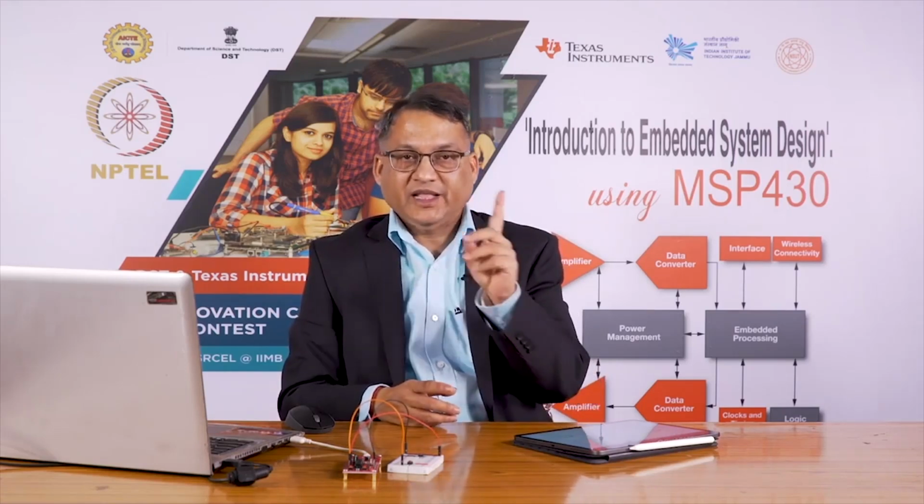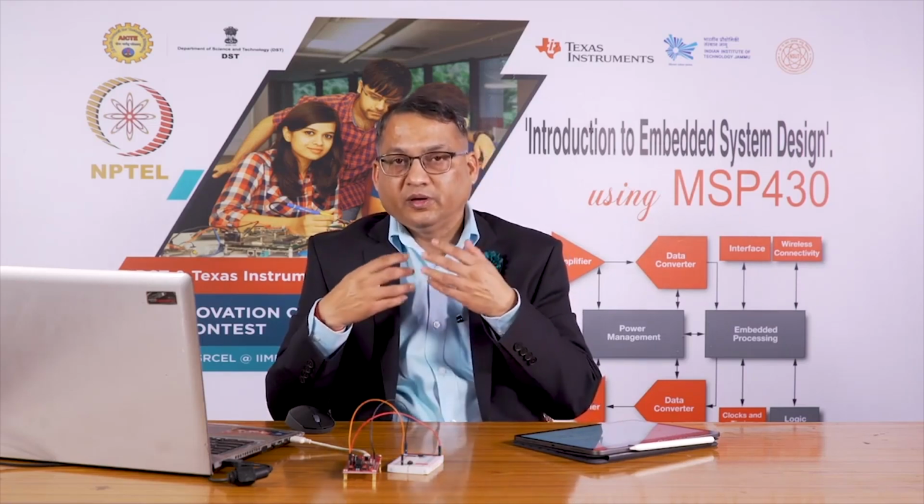So, I am not doing it here, but I recommend you try the same program by connecting a capacitor. This will do hardware debouncing, but as I mentioned, in embedded applications our aim is the cost, and cost means fewer components, which means we should avoid using an external component as much as possible, and try to gain that functionality by using software. So, we are going to avoid using a capacitor, and instead we are going to use software debouncing.